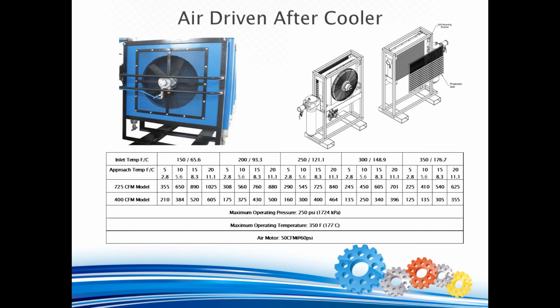These figures are approximately in the middle of the performance table and are used to rate the aftercooler and give it a model designation. However, to get actual aftercooler performance under different inlet temperature conditions, which is usually the output air temperature of the main air compressor, and target air cooler output temperature, which is the approach temperature plus the ambient air temperature, it is necessary to refer to such a performance table and not simply select equipment based on the aftercooler's model designation. Naturally, with a slower CFM airflow rate through the aftercooler, we have better heat exchange and also more moisture removal from the compressed air.